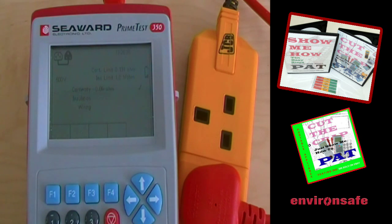Press the green button to start the test. And that is fine. The continuity is 0.06 ohms. The insulation is greater than 199 megaohms, and the wiring is OK.